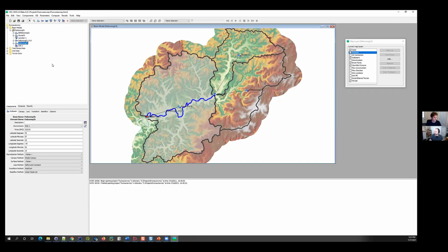All right, I've renamed the elements to my satisfaction. These are the names I'd like to move forward with, so they're good. The next thing that I'll demonstrate, it's parameterization, but it's also a GIS process. It's our new discretizations concept. So it's a way to discretize our subbasins. So I'm going to go to parameters discretization. I'm going to change the method to a structured discretization.